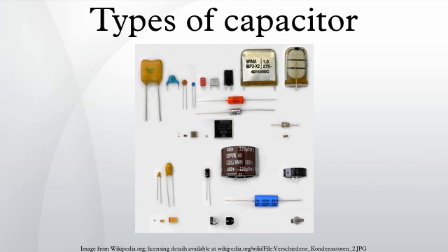Lifetime. Electrolytic capacitors with non-solid electrolyte age as the electrolyte evaporates. This evaporation depends on temperature and the current load the capacitors experience. Electrolyte escape influences capacitance and ESR. Capacitance decreases and the ESR increases over time. In contrast to ceramic, film and electrolytic capacitors with solid electrolytes, wet electrolytic capacitors reach a specified end of life by reaching a specified maximum change of capacitance or ESR.